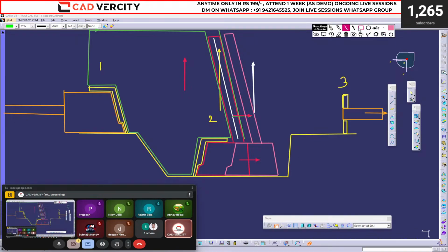Again, this is an interview question. See, tell me, suppose like this wall, if I add something over here, let's suppose this is a rib, will it be okay? No, sir. The rib will break, sir. It means, sir, we don't have sufficient space for the travel of the lifter. Yes or no? In technical language, yes. We don't have sufficient space for the lifter travel.